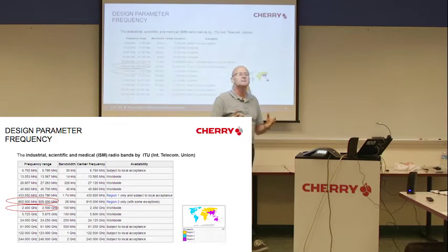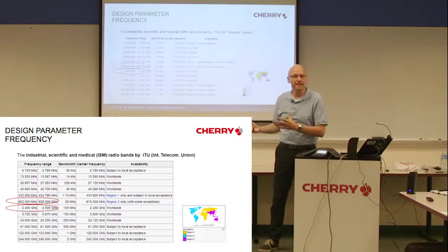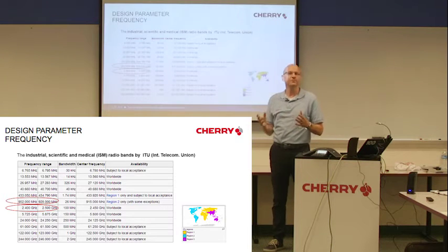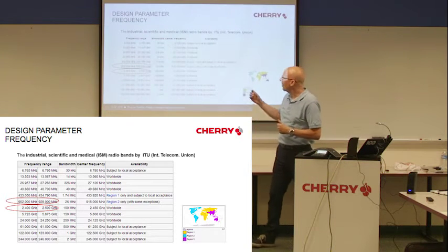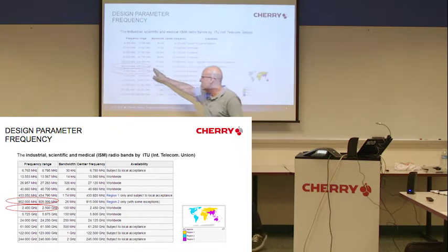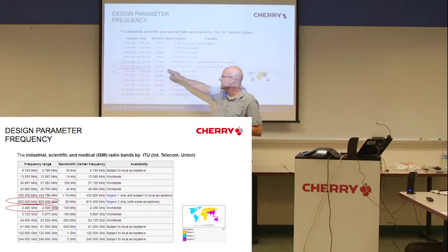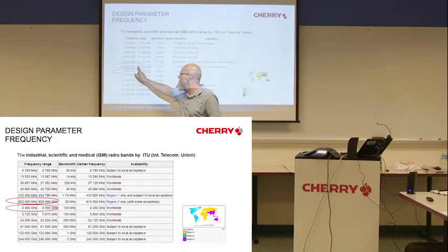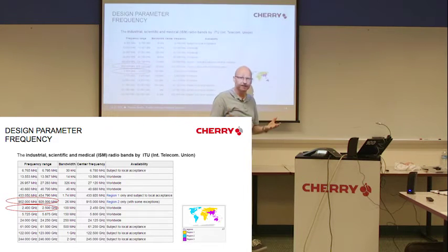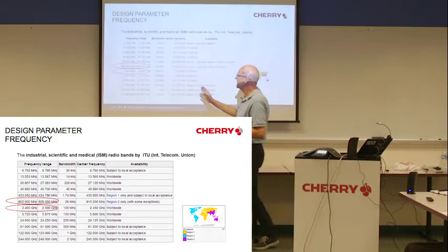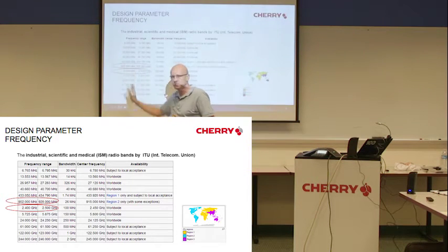So when we speak about a 950 megahertz protocol or an 868 protocol or 2.4 gigahertz, then we always mean this band. But 950 is the center frequency in the middle of this band, and so we say, okay, it's 950 megahertz. But it's always a band. You can use one frequency of this band.